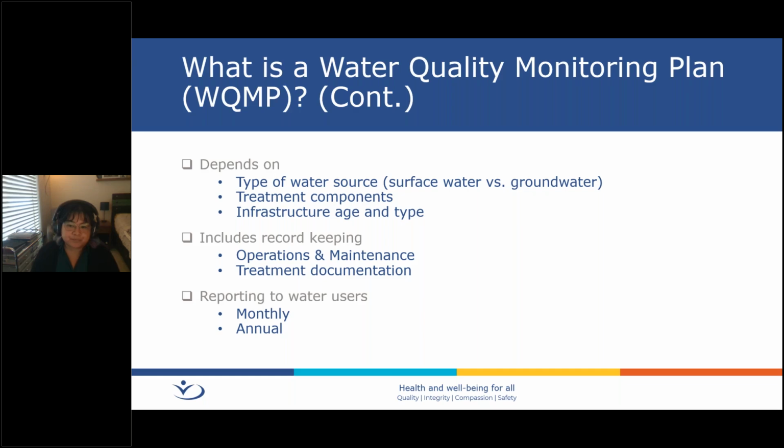And by reviewing the chemical, physical, bacteriological test results of the raw and treated water, any adverse or unacceptable test result can suggest that there's a need to look closely at what the source of contaminants would be. So this is part of developing the monitoring plan.